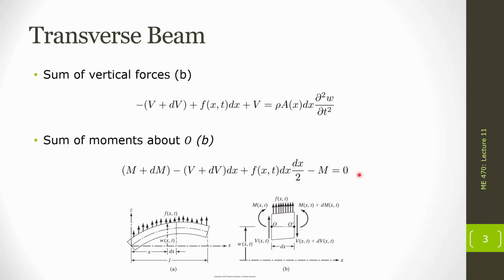And we are going to presume that in these transverse beams in bending, these segments do not rotate. They experience only a vertical displacement, but not a rotational piece. Therefore, the right-hand side we can say is 0. There's not going to be rotation considered for these beams.